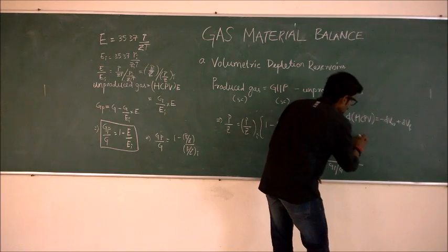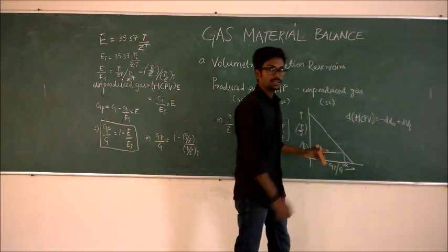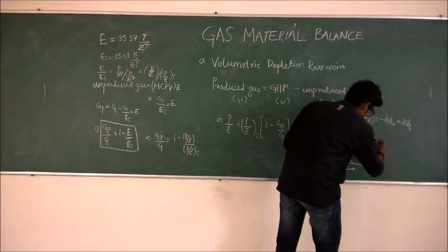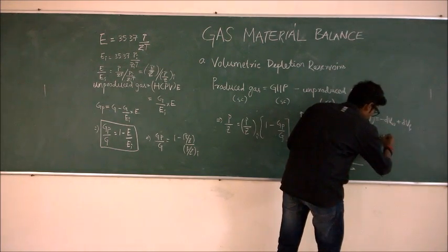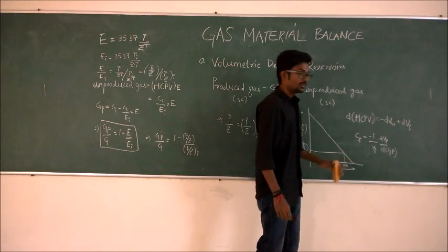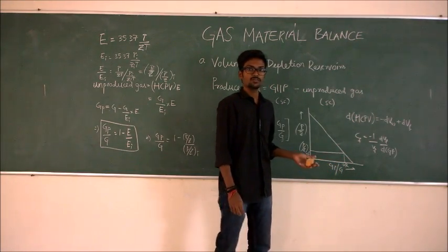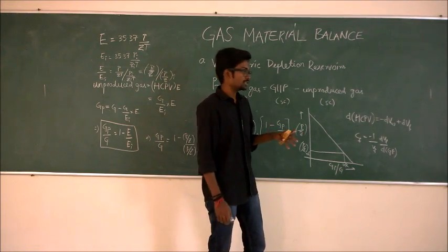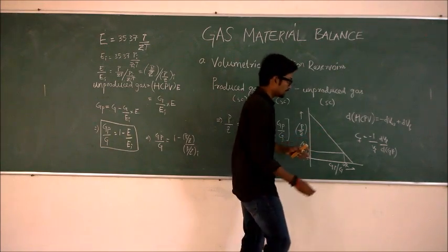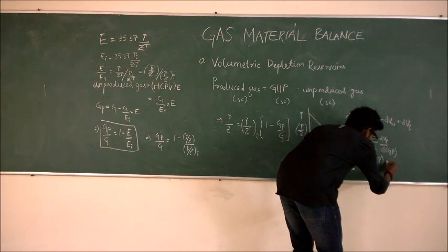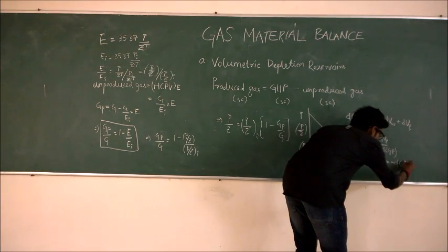So now coming to the isothermal compressibility of the pores, which is given by Cf is equal to minus 1 by Vf dVf by dPg. Here Pg is the grain pressure, but we know that overburden pressure is the sum of fluid pressure and the grain pressure. At a particular depth, overburden pressure remains constant. So, with respect to depth, the change in fluid pressure is the minus of the change in grain pressure.